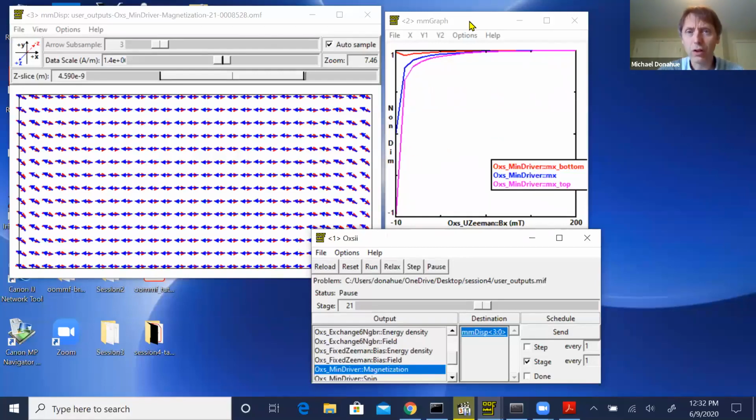Okay, well, I'm going to show you another trick on an OOM graph. If you place the cursor on the left axis and you click, and see if I can get it here. No, there we go. There's a little movable axis. Okay, and the coordinates here by the arrow, that's the coordinates of the arrow point. So there's 46. So I can move this down to, for example, close to 0, and that's where the 0 axis is. Okay, and likewise, there's another one down here, which I got first try. You can put this anywhere, and it helps you see how flat things are. You can read off what the values are.